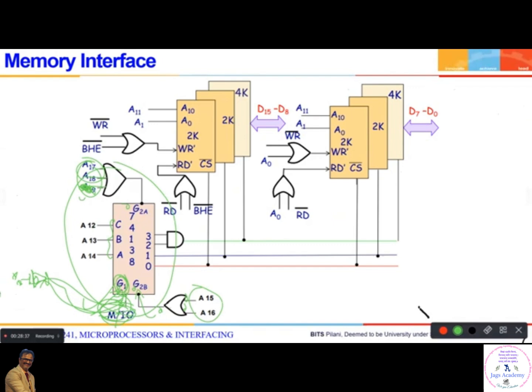But absolute addressing mode. Remember, absolute addressing mode means that as much as possible you have to connect address lines and control signals as inputs to the decoder logic and the selection inputs. Incremental addressing, no problem. You permanently make this VCC, permanently make this ground. Okay, this one permanently make ground, no problem. Absolute, no problem.